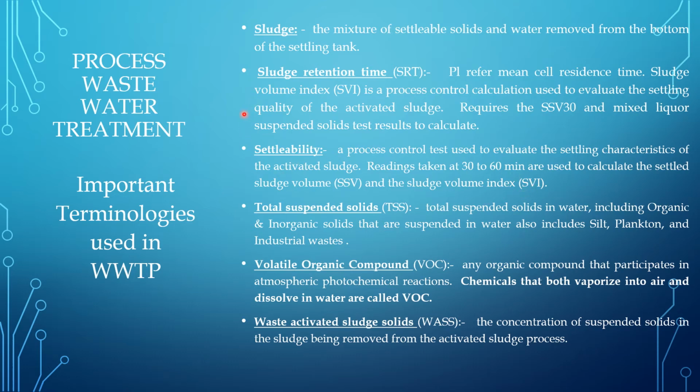Same one, the sludge, initial time, settleability. How a process is settled is called settleability, and that will play a vital role based on the activated sludge. If it is more, we have to recycle it back, and if it is less, we have to produce more.